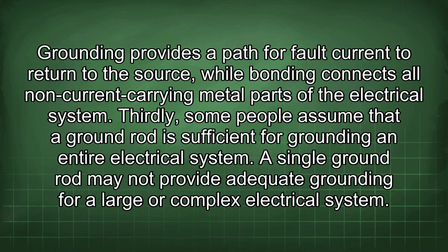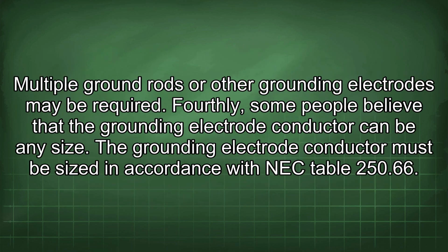of the electrical system. Thirdly, some people assume that the ground rod is sufficient for grounding an entire electrical system. A single ground rod may not provide adequate grounding for a large or complex electrical system. Multiple ground rods or other grounding electrodes may be required.